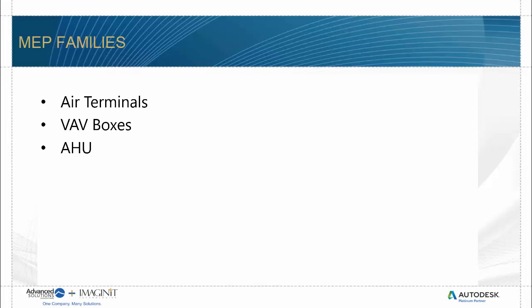Again, after that, once we get everything laid out, once we get the idea of what we're going to work with, we want to start putting in our air handling unit. We want to start putting in our air terminals. We want to start putting in our VAV boxes to start getting that design coming to life. Getting the information in to use based on our needs, getting the design criteria in so we can look a little bit more in depth, again, using our space schedule to work and doing design checks, getting things in based on our needs and based on what the client wants as well.